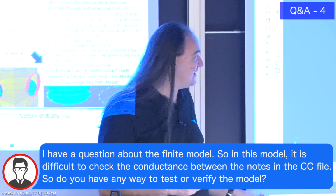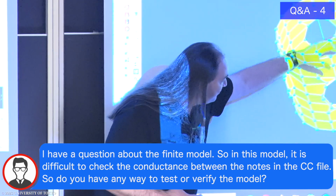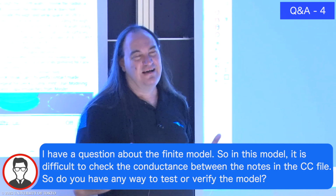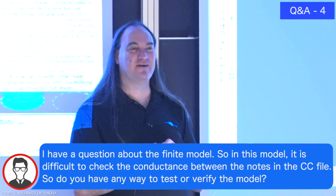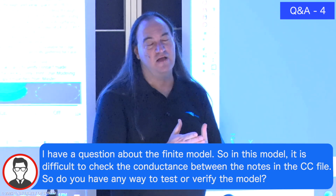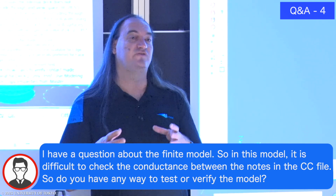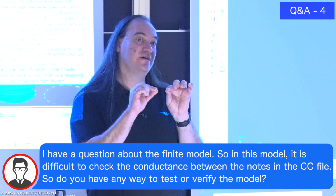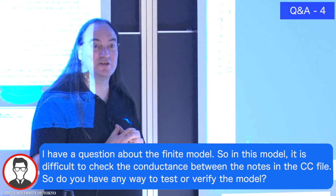But do I really care about the heat flow between here and here, or do I care more about the heat flow between this quadrant and that quadrant? So from my point of view, I trust that it's correct. It's one of the things I have left to do in my career is to truly understand how they get the conductance matrix in there. But I usually am looking at this group of elements to that group of elements, or this group of nodes to that group of nodes. And so I'm not interested in, per se, one conductance path. I'm interested in the conglomerate of many of them. Does that answer the question? Okay.